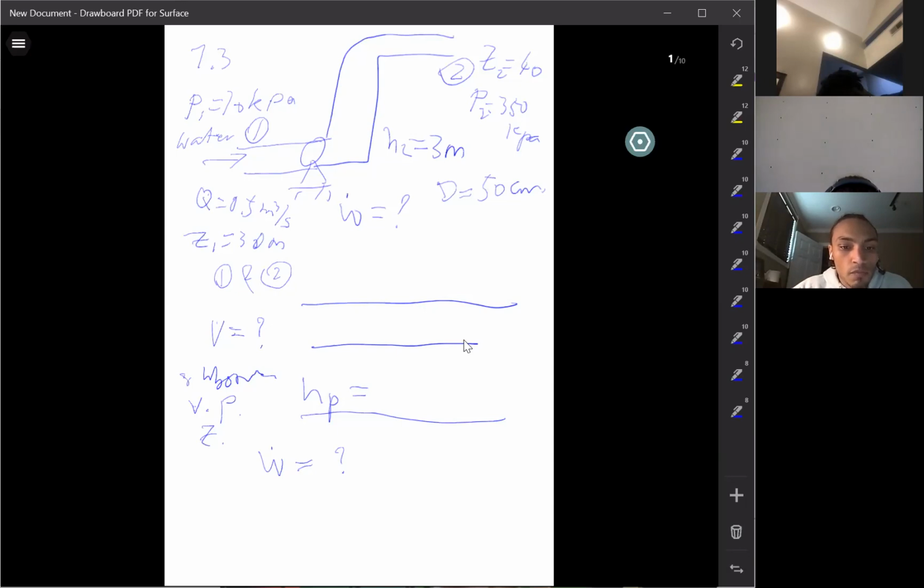Think about it. Even if I change the pipe size in the discharge, you can basically calculate the velocity two times. The flow rate is always the same, so you can calculate V1 and V2. So it's not really more difficult. It's just more time consuming, more detailed, but it's not difficult.